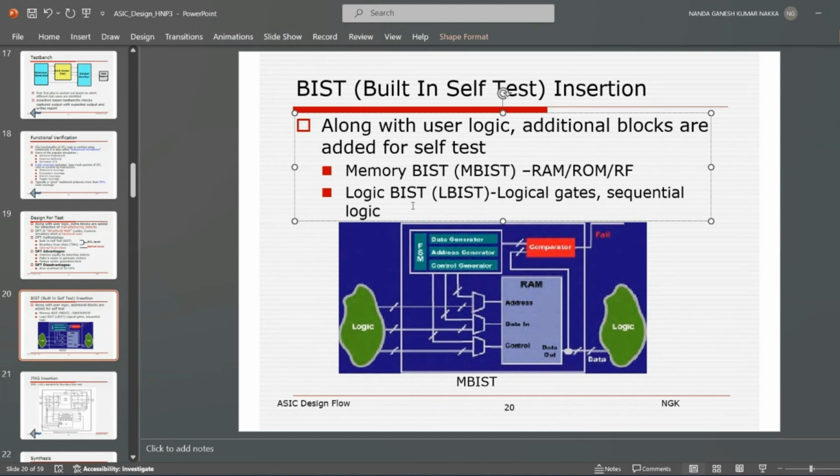Now, this is one methodology. You can do it. This is for memory based. This is your memory based logic. What you are trying to do is, this is your SoC, the architecture. Considering this is your total SoC, from this level you have all the primary input ports, and these are the primary output ports. Now, without DFT logic, that means BIST logic, what happens? You have a direct connection from this to these memories.